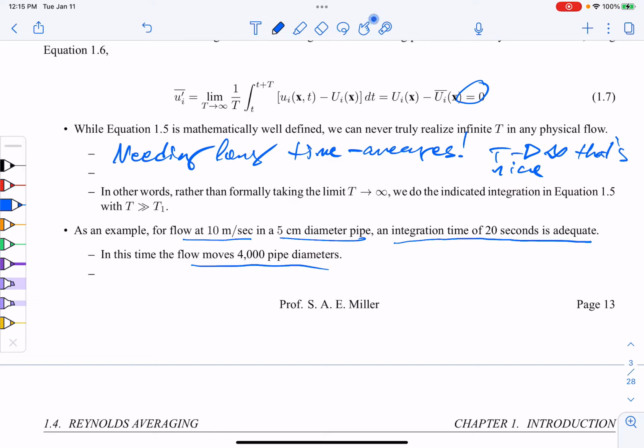Another problem often encountered is that flows may not have a nice single value of an average. It might be periodic, and you might think of flows where that's the case. I can think of one right away, and that's a rotorcraft, helicopter blades. The turbulent flow over those might be periodic in forward flight, with the periodicity going as the rotational speed of the helicopter, right?